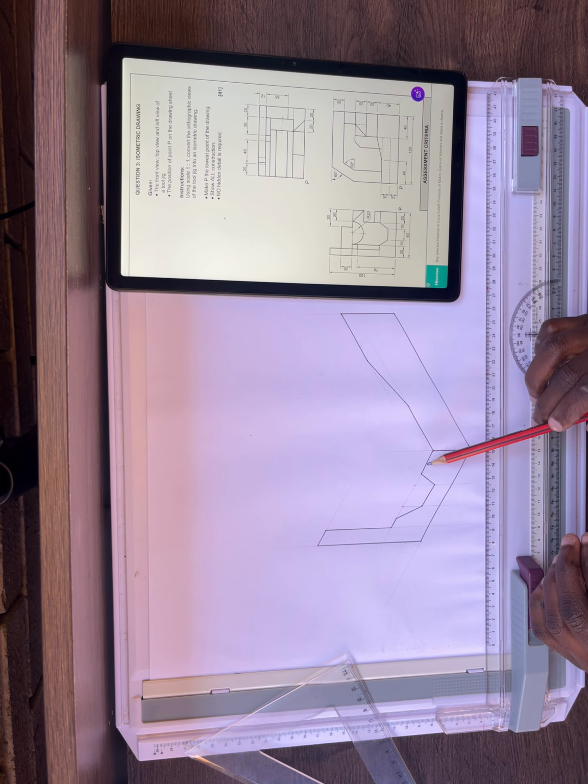There you have got your piece. Then let us go through all the pieces that should join here. If you can check, they must be coming from either the top view or the front view. But if it's an isometric line like this, it means that piece must come from the top view, because this line we are taking as it is facing the top. This one does face the top, but some parts of it do face the left view.